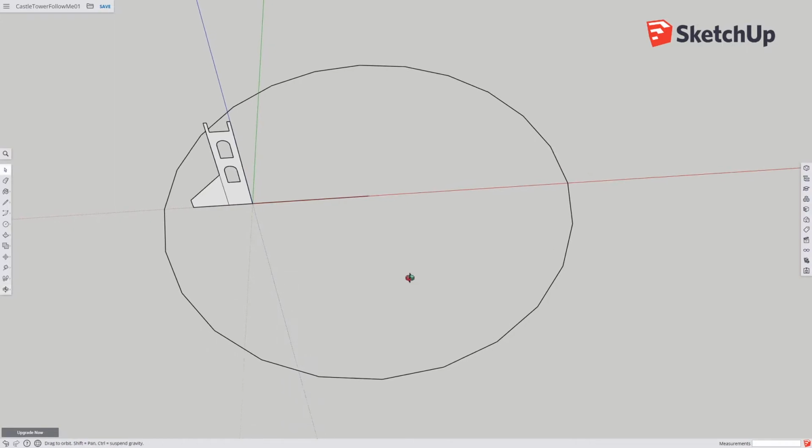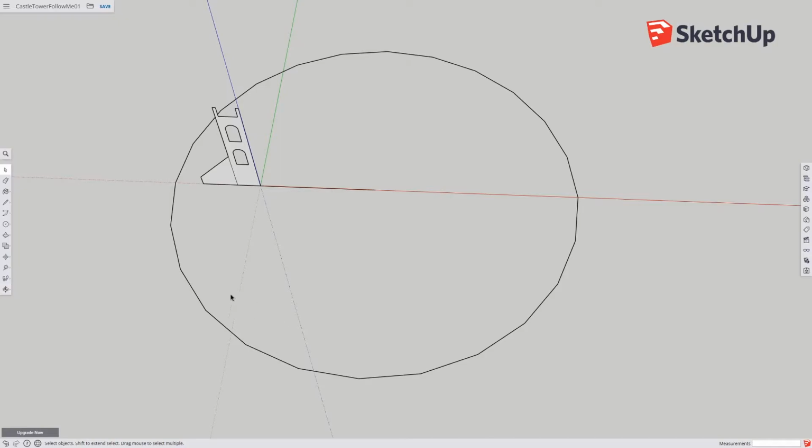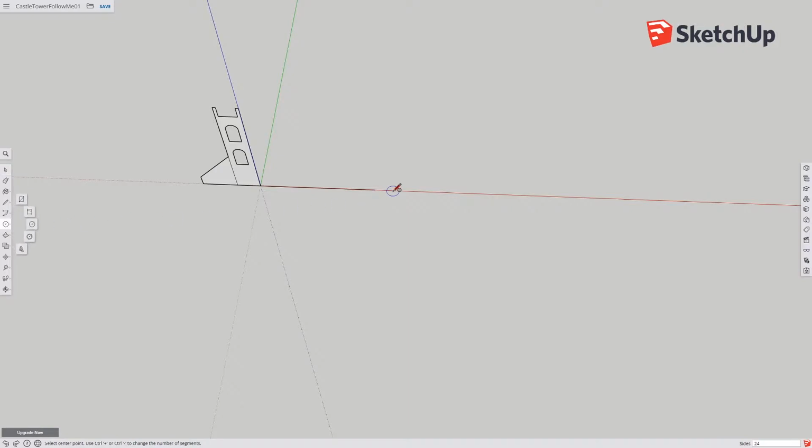Now, as we spoke about, and as what SketchUp does, it doesn't do a true circle. It does a polygon, a multi-sided shape. The default, I'm pretty sure, is 24, so it's a 24-sided shape, which looks like a circle. And I tended to make that really high resolution, so I think it's too late for me to type in now, but I'll do another one. I'll do a circle here. For you guys on your little Chromebooks, I wouldn't overdo it.